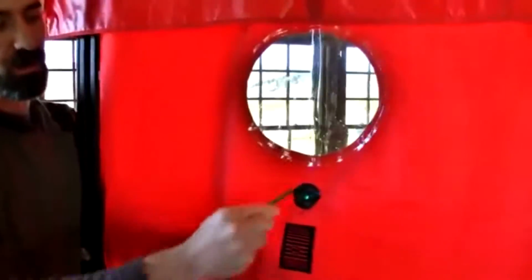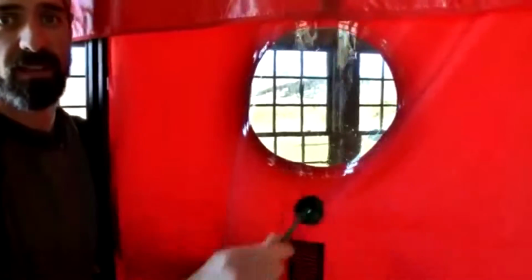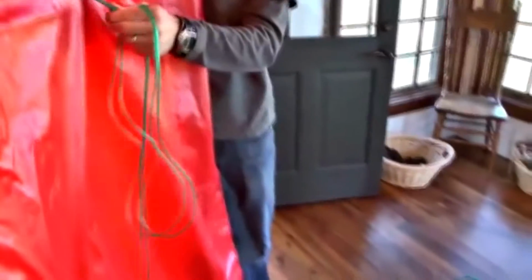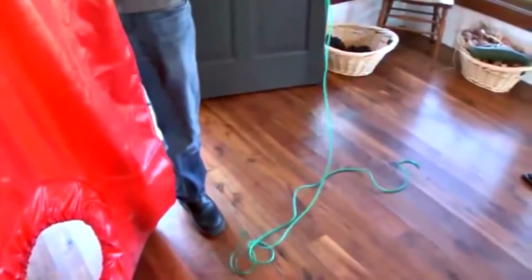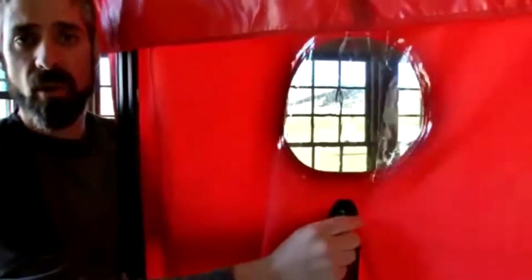The big thing to be aware of is that you don't just pull out enough so that it's hanging down in front of the fan, because that's going to give you a bad reading. So we like to pull out 15, even 20 feet, at least so we can get it out of the way of that fan. If you're dealing with a porch outside, for instance, a closed-in porch, you want to make sure you pull out enough so you can get it to the outside and not just into that porch area.